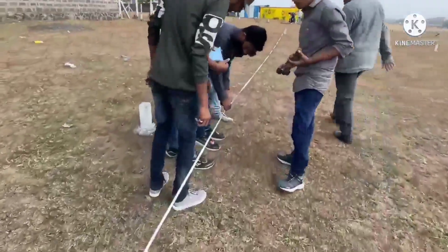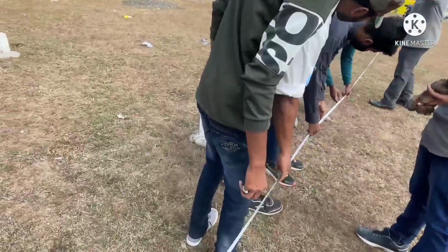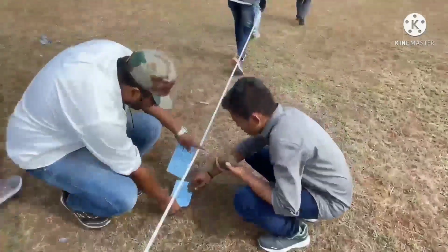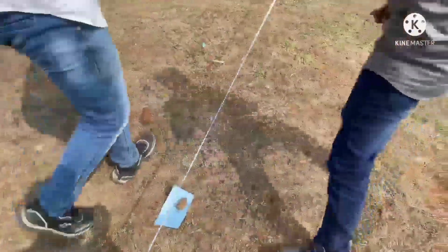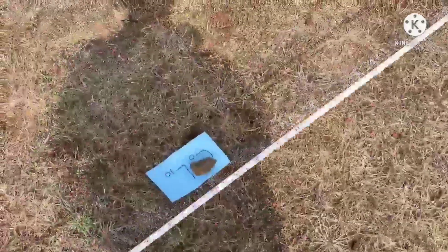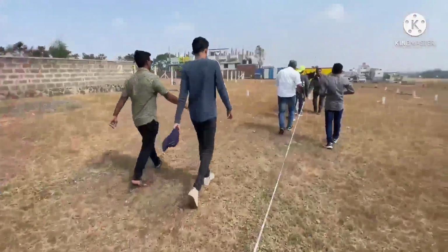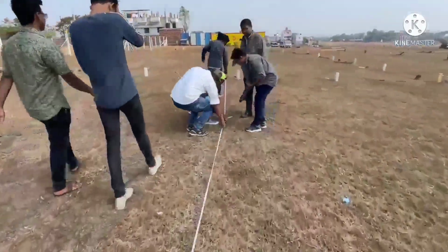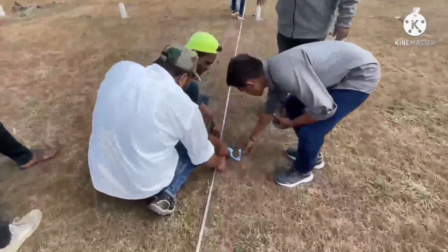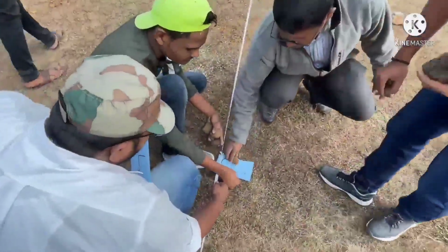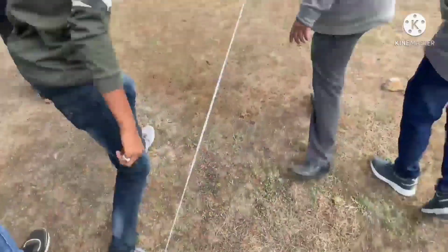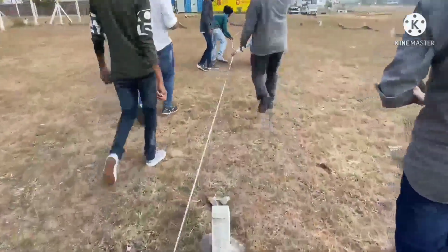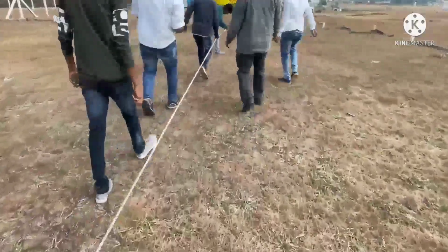So here we are getting the distance of 10 meters. Okay, so here will be the corresponding, this is the left hand side, so that will be nothing but C0 L10. So that is chainage 0 on the left hand side at a distance of 10 meters, that is nothing but C0 L10. Other will be C0 L20, because from C0, that is from the center point, we are moving at a distance of 20 meters on the left hand side. Similarly it will be C0 L30.